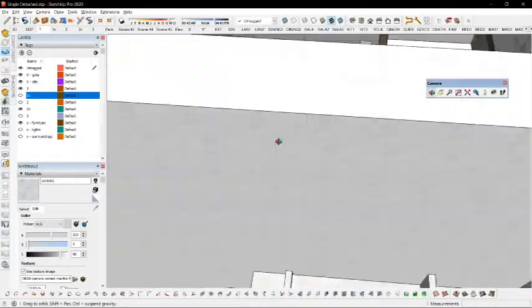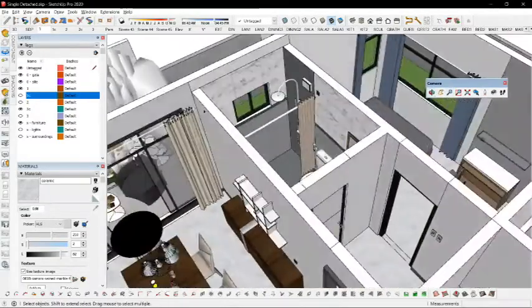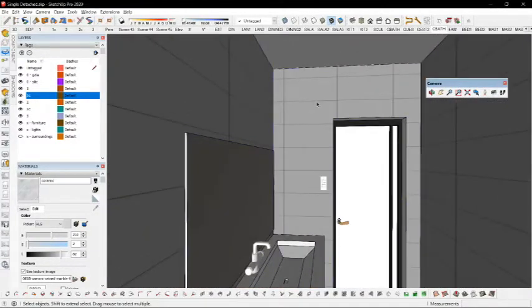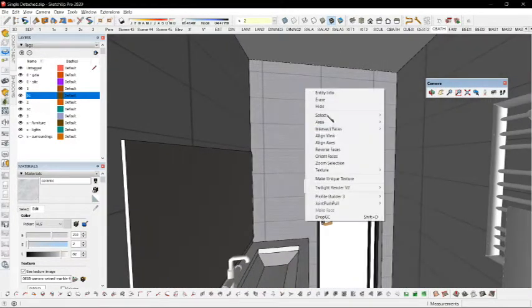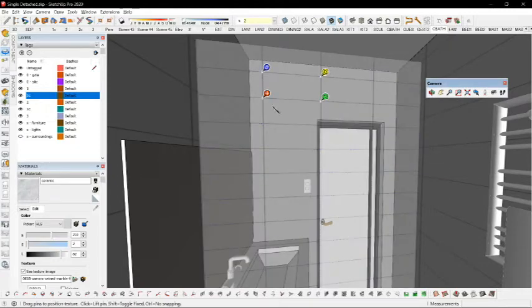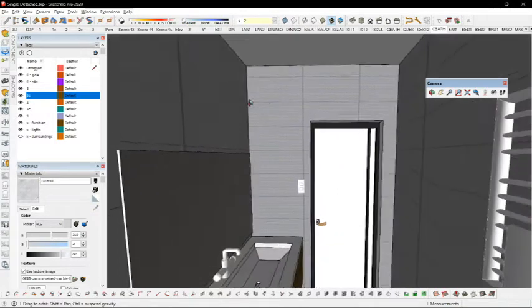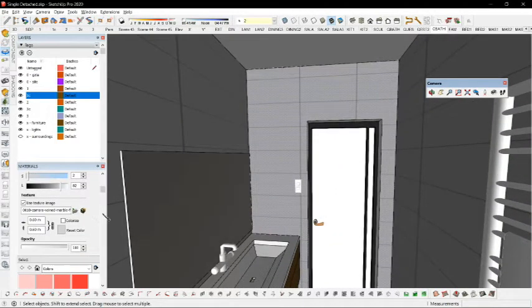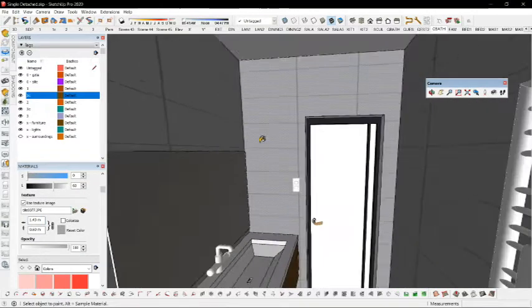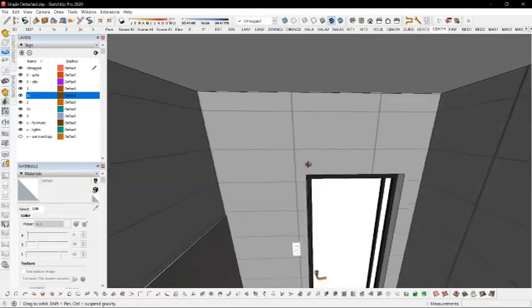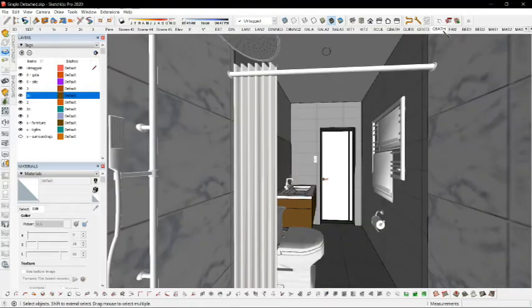You could also fix your texture so you don't have to keep modeling, let's say, all the tiles. You could actually fix this so that when you are constructing, you could tell them just to follow the layout. You want it to start from the left, then go here to the edit material and put the dimension, if it's a 60 by 60, 30 by 60, as long as the image is exactly 1 tile. It's showing an experiment.